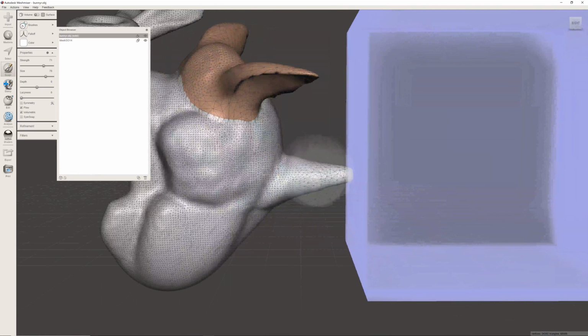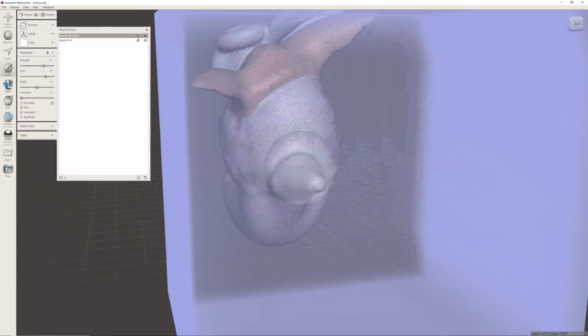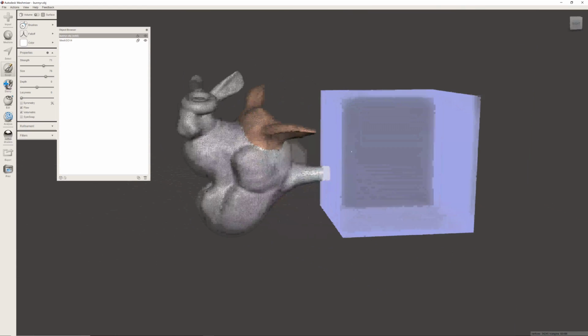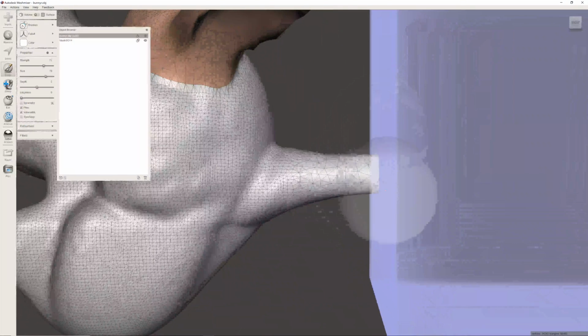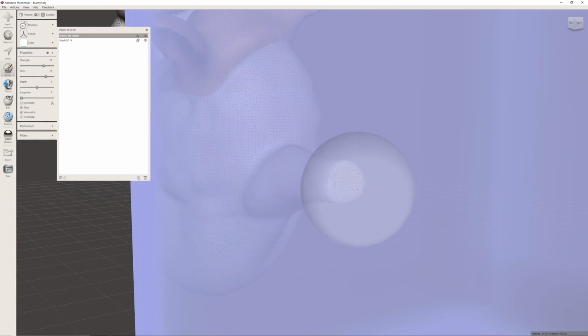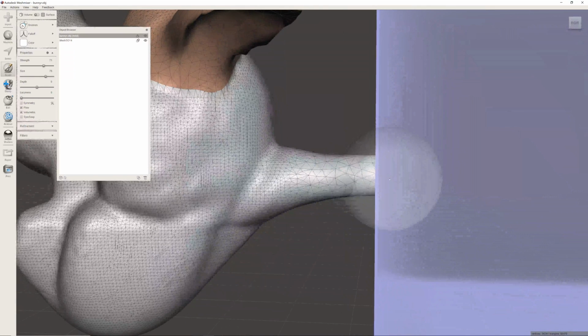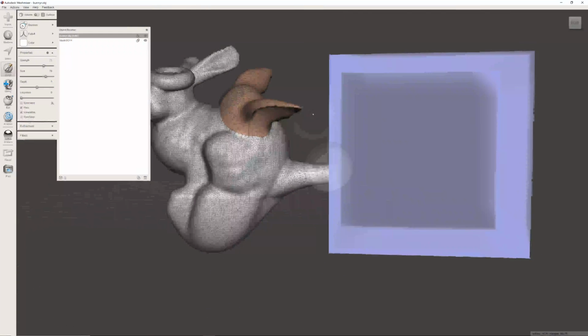So you can see that slowly this mesh is being moved to our target. We can attract more and more, create more surface. So these two surfaces are now flush with each other. This can be helpful also to create two objects that you need to connect. But remember, if you want to unite them, there needs to be some intersection. They can't be right on flush because booleans, in any software, won't work unless there's even like a 0.001 intersection between the two meshes.